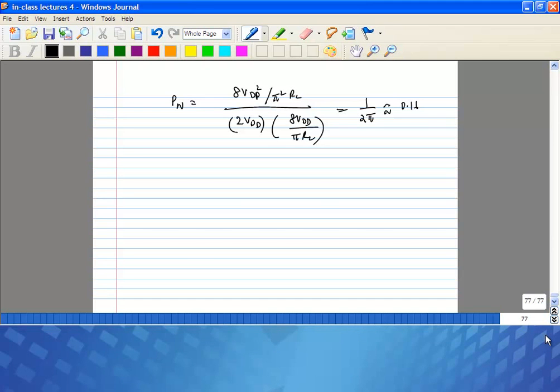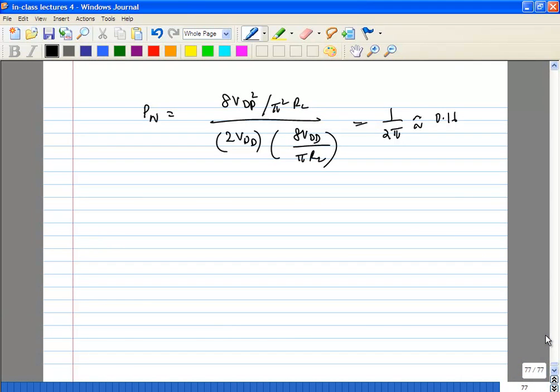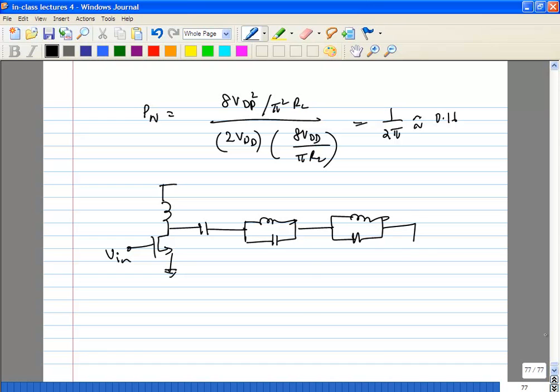So the next thing to do is use lumped LCs. What you are trying to do is very simple: you are trying to reject certain harmonics. Start using tuned circuits, either series or parallel tuned circuits, to reject harmonics. For example, this is tuned to omega naught, the original one.